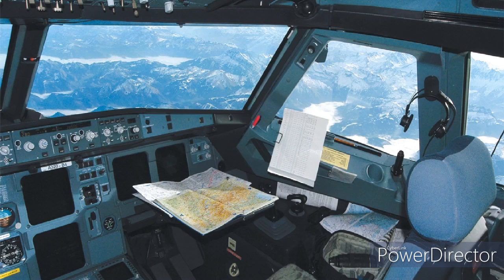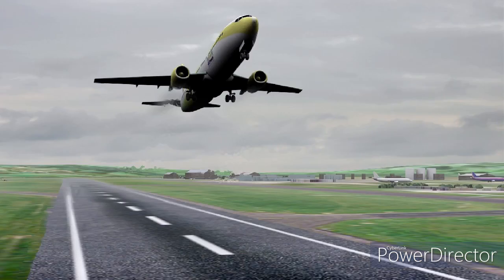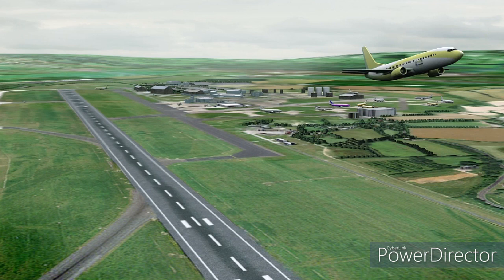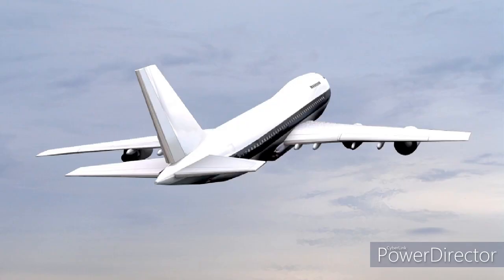The different levels of engine power are nominated by the following terms. Takeoff thrust. Maximum thrust available from the engine. This power setting is normally time limited. Go around thrust. This power setting can be the same as that for takeoff thrust, but it's normally a slightly lower value. Maximum continuous thrust. This power setting is the maximum level that can be used continuously.